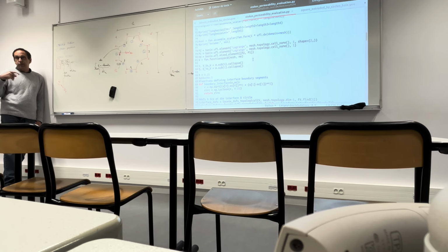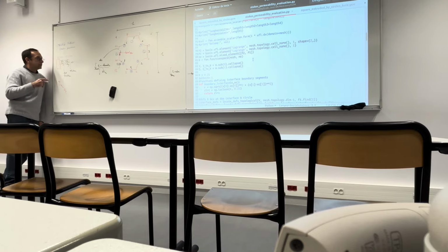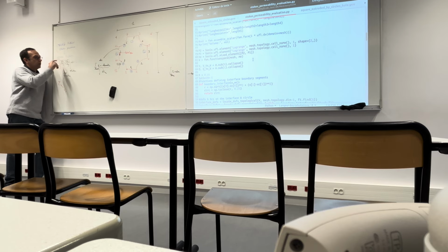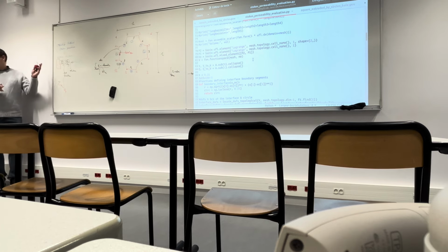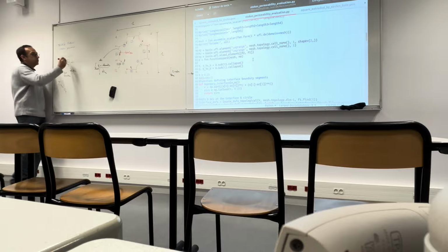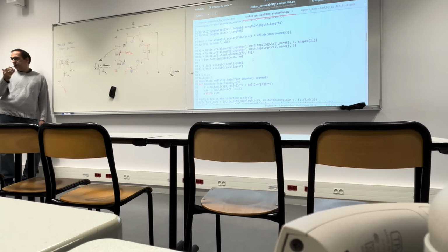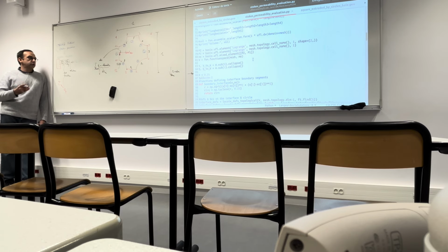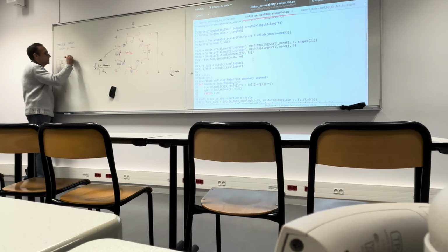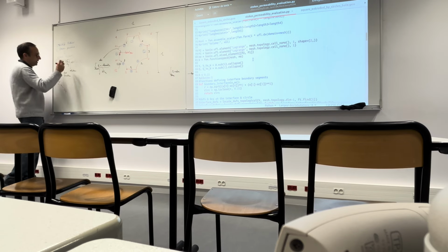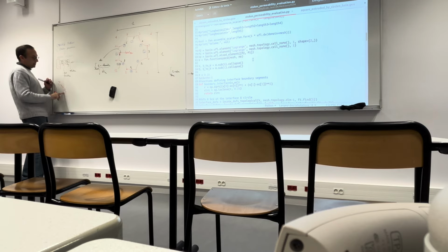But the second and most important part of the story is that you look for a special kind of solution. So you look for solutions which are combinations of suitable shape functions. No? So you choose what are the functions you are going to project on the solution and the test function, and you represent, for instance, the ui over the domain dE.